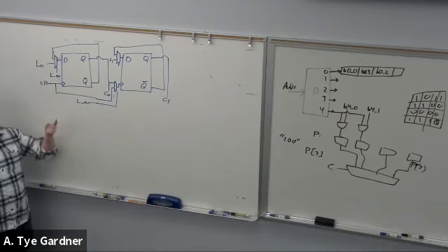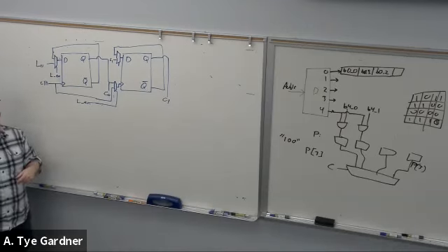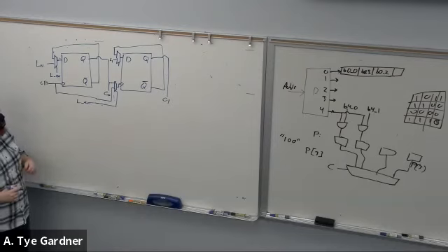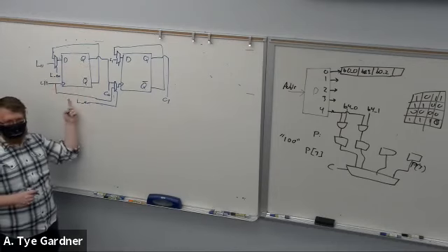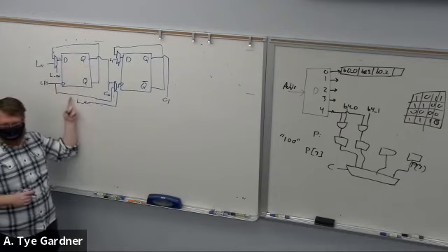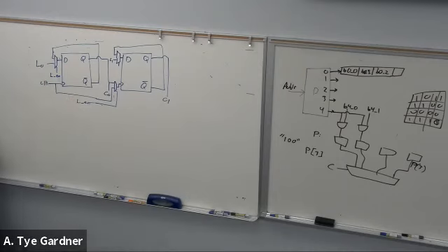Right now I'm just taking one clock or the other one. And so if load enable is turned on, I'm no longer dealing with the asynchronous clock, I'm dealing with a synchronous clock. So it becomes a synchronous load, which is probably a good solution.